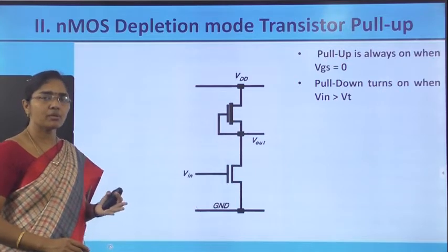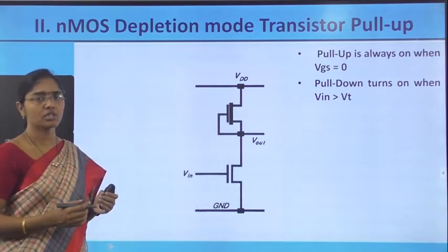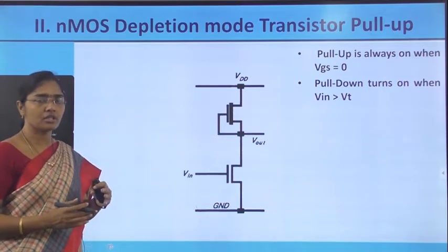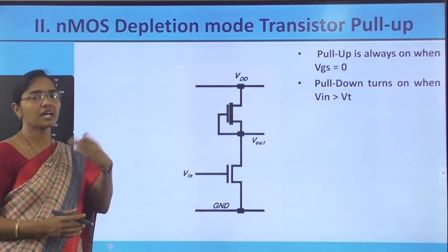In the resistive pull-up device, the only problem is that because RL is used as the load in ICs, it will take more space. So, it is not preferable. So, that resistance is replaced with a MOS transistor.